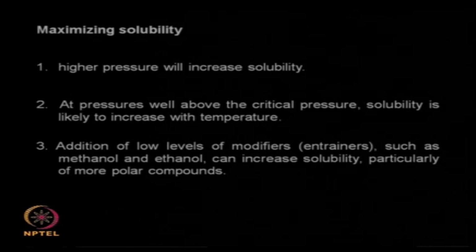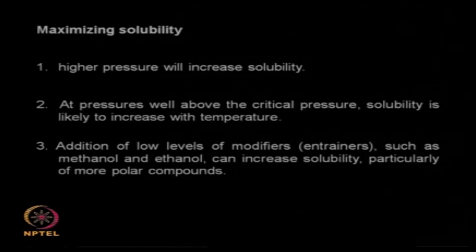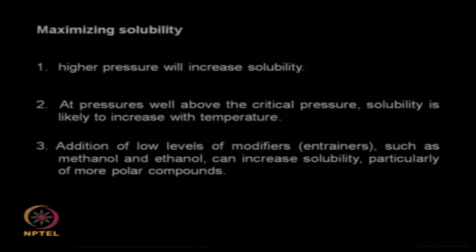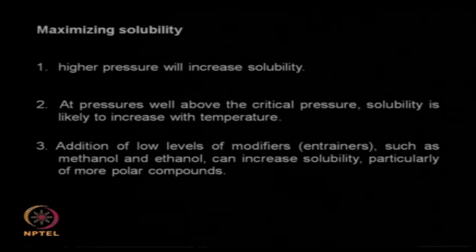So you may have to cool, that means you need to put in a cooling system to cool the supercritical fluid. Sometimes addition of methanol or ethanol modifiers can increase solubility, especially for more polar compounds, because as I said CO2 is non-polar.